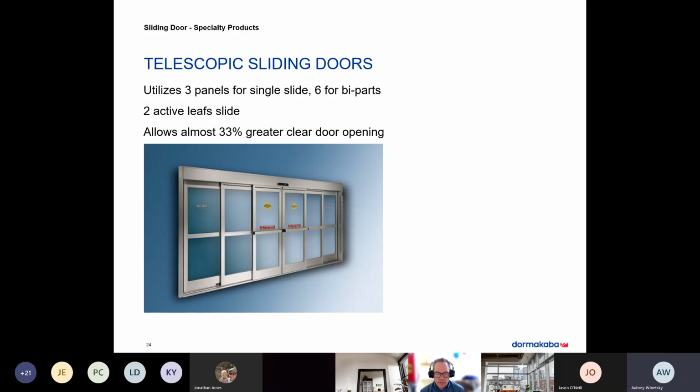And the drive systems on these doors, all of the manufacturers make their drive systems capable of handling heavy traffic loads. So I would say the only reason to worry about the glass would be in a breakout situation. But even then, they are reinforced. You might have the corners welded, or they've got reinforcement threaded rods inside of those styles to help keep everything very supported. So the sliding doors place a lot less stress on the glass than the swing doors.